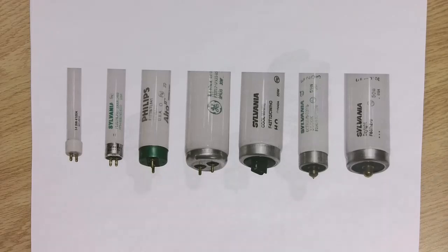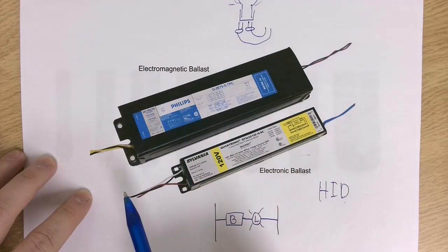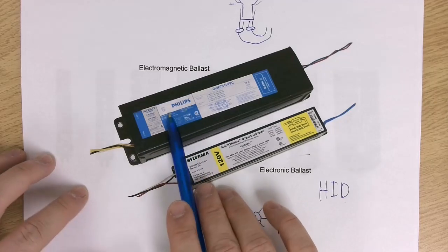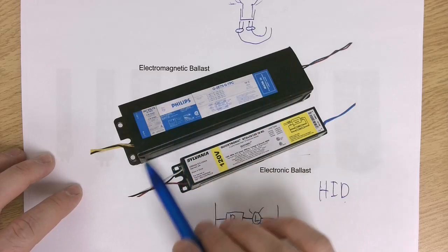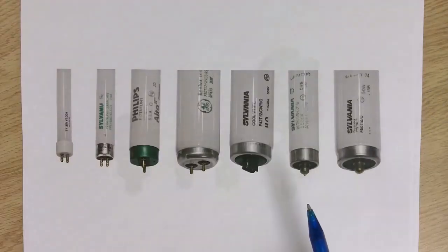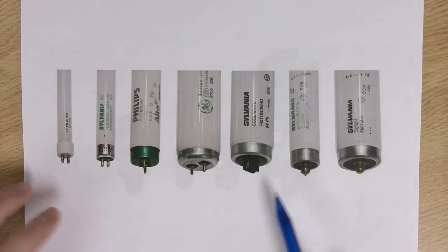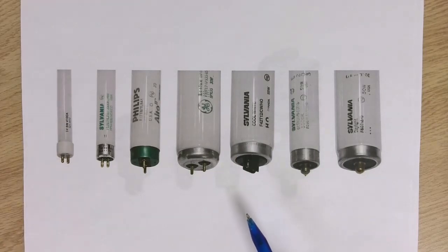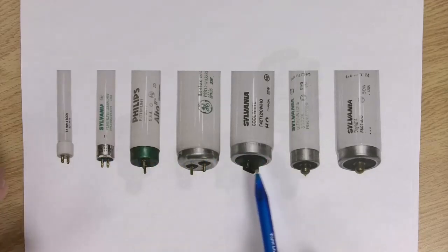And just to go back to the ballast picture for a second, if you're changing out one of these old style types of ballast, this electromagnetic ballast, they are quite heavy. They can also be very, very hot. And sometimes they crack and leak out all these nasty things, which can be also hot. So just be careful and watch yourself. But be extra careful that you're replacing the ballast with the correct or the same ballast, basically, because different types of lamps require specific types of ballasts.